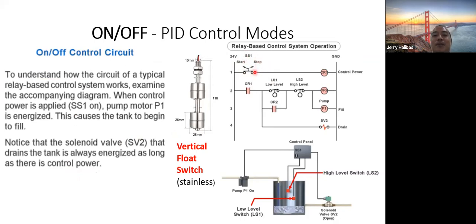A selector switch is possible, but as much as possible, normally push buttons, so that you won't forget that if there is an overload in the system, it will break right away. This one, you cannot break because it's using selector switch SS1.